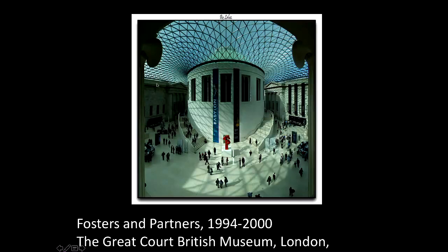So before, you would have window mullions or glass with mullions, and then underneath some type of structure like a space frame that was held up with columns. But the big step taken here was, no, the mullions holding in the glass are also the structure.